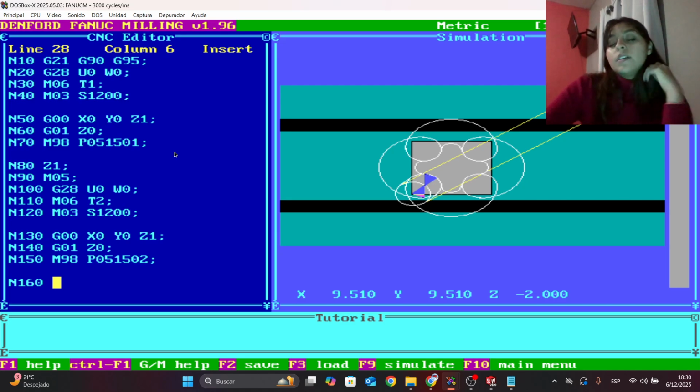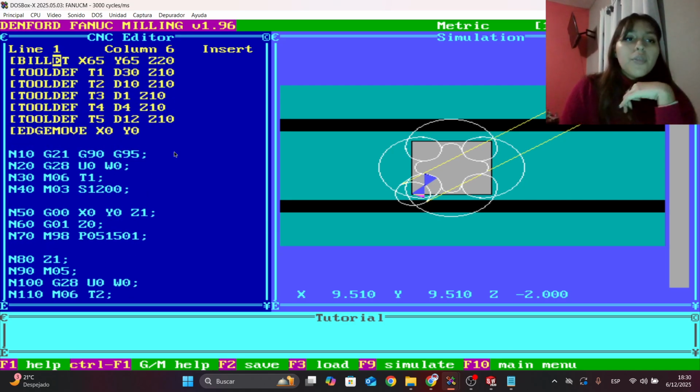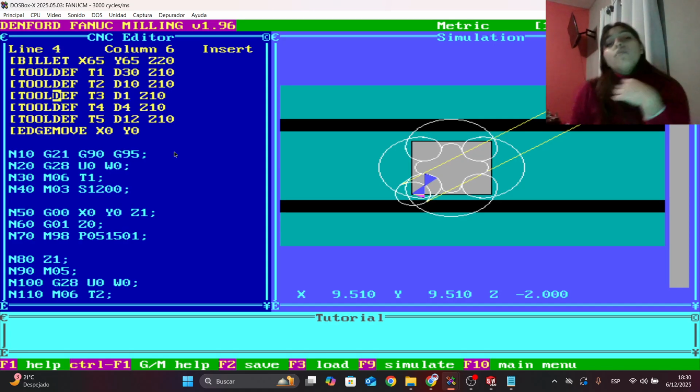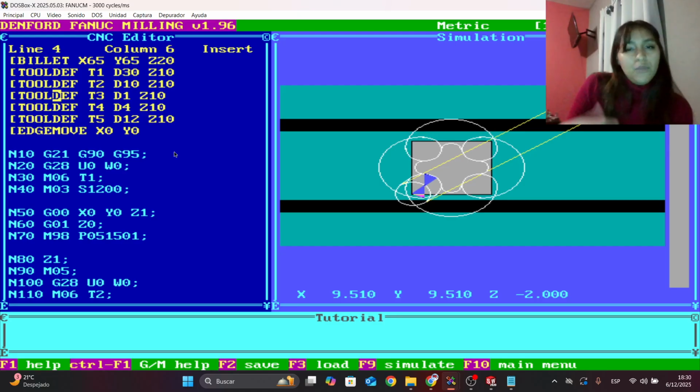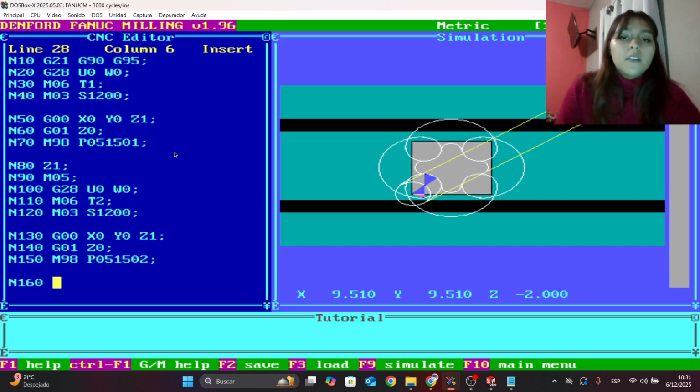We're going to use the tool number 3, the one from 1 millimeter, so we are going to be very close. Actually, the T3 is the one for the finishing parts. So we're going to do that, and after that we're going to see how long we have to keep doing cycles to get all of the material out. I'm going to repeat all of the writing of this part, and I'll be back.